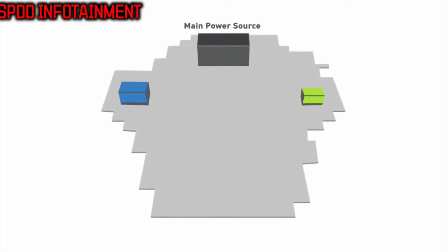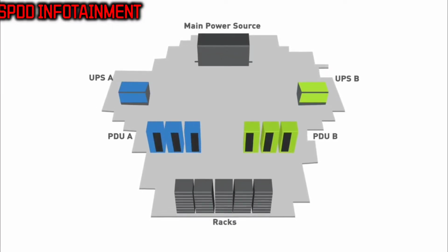Each rack should have 2 outlets from 2 different RPPs attached to 2 separate UPSs as part of a redundant power chain. The rack PDU in each rack plugs into the outlets. Most servers now have 2 power supplies, and it's important to plug each power supply into a different rack PDU. This way, if a UPS should fail, then the connected floor PDU and RPP will fail, and one rack PDU will fail. If properly configured, the other rack PDU along with the other power chain will remain operational and your servers won't go down.